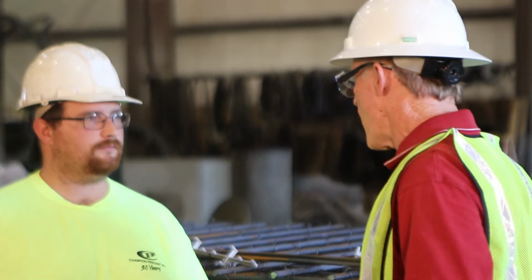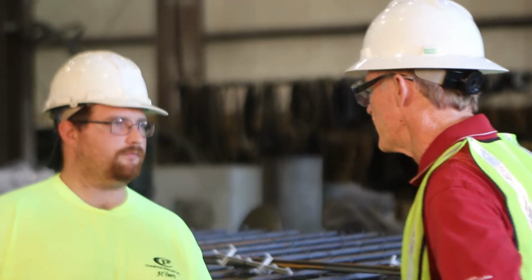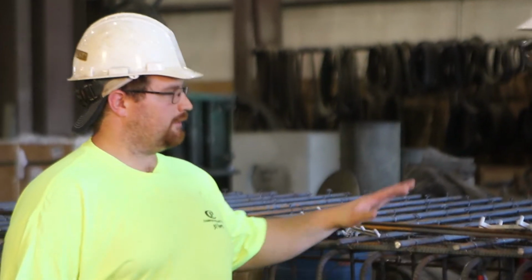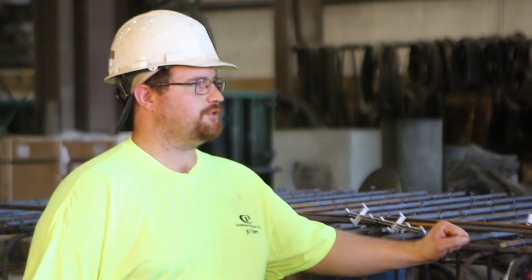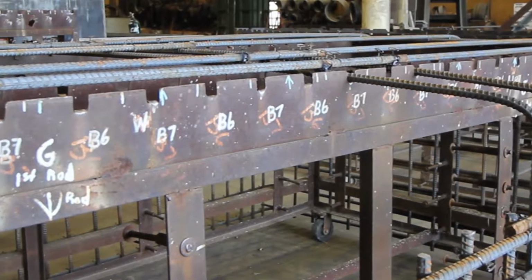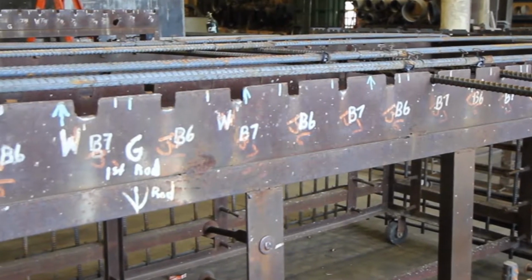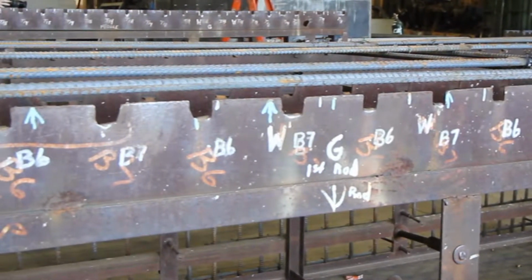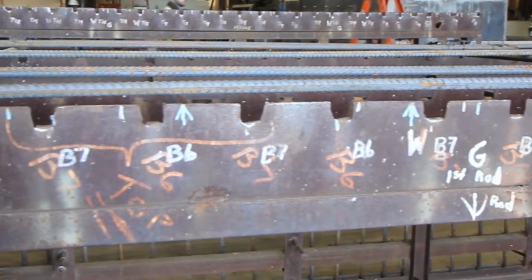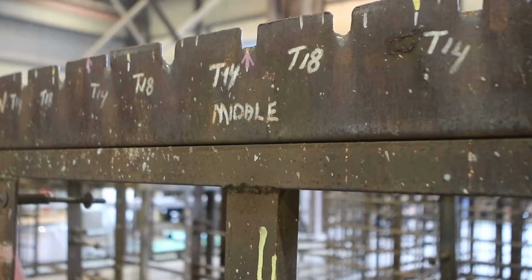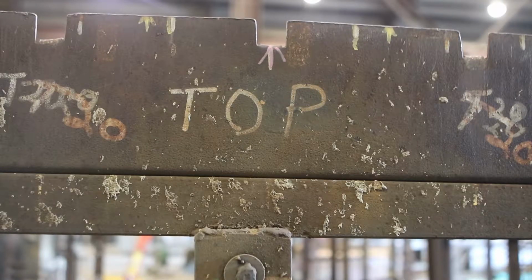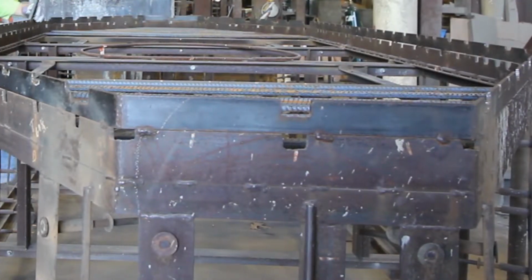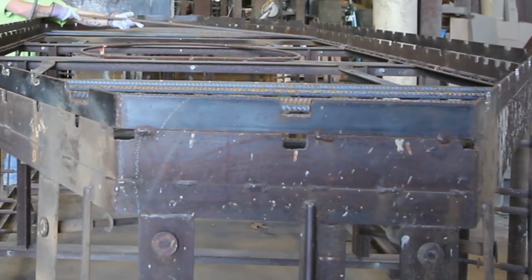Okay. All right, Michael, so let's say you need to build a cage and your form is being used. How would you go about constructing your cage? Here at Champion Precast, we particularly like to use reinforcement cage jigs. These jigs provide the ability to construct a sturdy and transportable cage. Also, this jig adds additional speed and quality assurance by having bar placement location within the accepted tolerance range for the product. The only variable to be the bar size, which is shown on our shop detail. Additionally, this fixture can be marked to show any special layouts, such as cast openings or embedded items, lifters, etc.